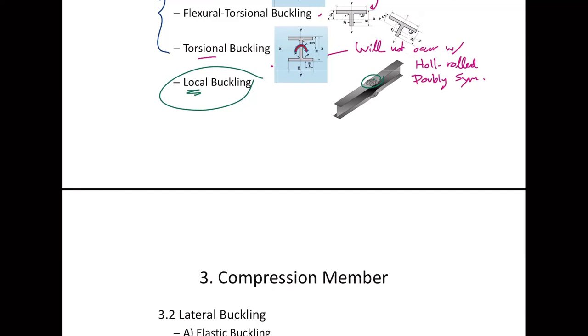Yeah, but I just want to ask if the real pin support we use in the design, is it going to be able to rotate in all axes? Good question. You want pin, you better make sure that you give detail to the structure so that upon construction it should be pin. Correct? Remember, we are engineers, so we can dictate the behavior of the structure by giving proper details so that it behaves the way we want.